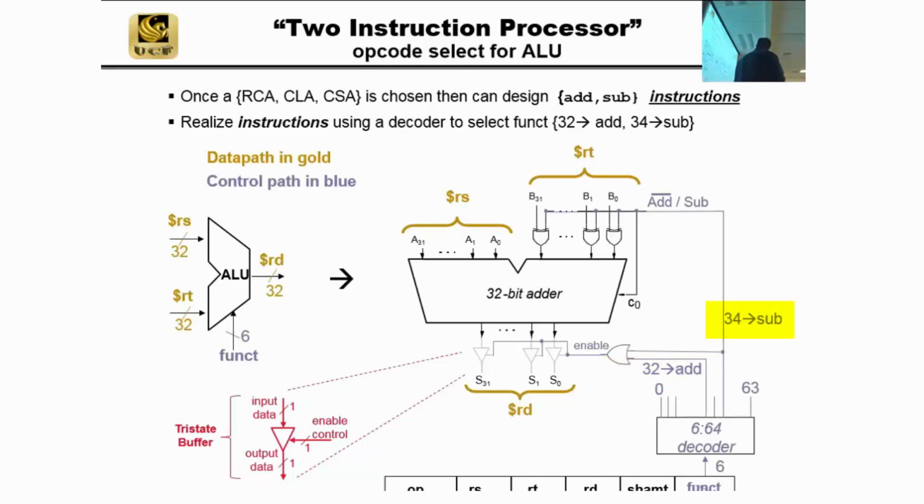So basically, when this instruction is executed, these bits of this field are hardwired to a decoder. One of these lines is lit for each case, and then I can AND or OR this in the data path to realize whatever operation I want to execute. This is very cool because it lets us design a processor from Boolean gates, taking the input and decoding it. So if it's an add, this line is hot.